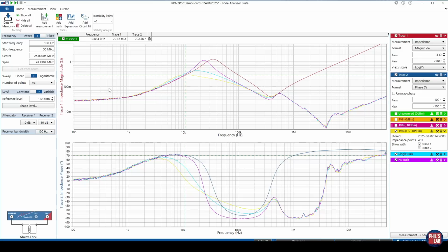Now this is pretty cool. We can quite clearly see, first of all, that this peaking or resonance frequency is also shifted because we've gotten rid of another 10 microfarads of capacitance. But of course, this high frequency region, which is typically dominated by these multi-layer ceramic capacitors, is now effectively non-existent. We have this parallel resonance before we immediately then go into this inductive region.